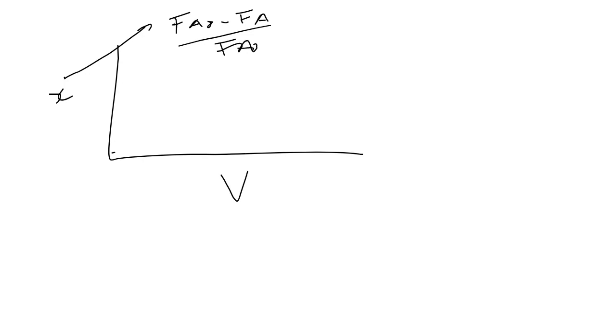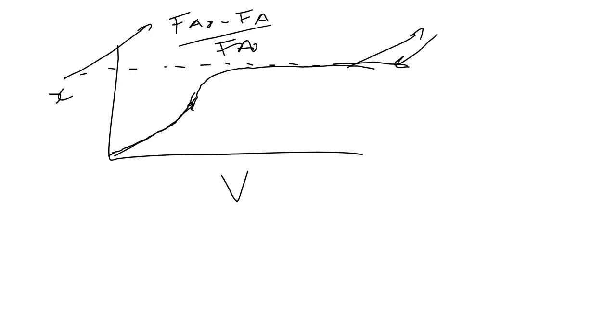The rate is going to increase until that maximum value where you're going to operate your CSTR, but the PFR goes past that point. The rate starts to decrease, and then it's going to look exactly like those profiles you were drawing for that 4.1 when I asked you to draw that profile. And this is that maximum conversion where it is going to stop.